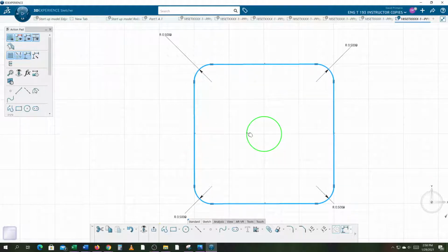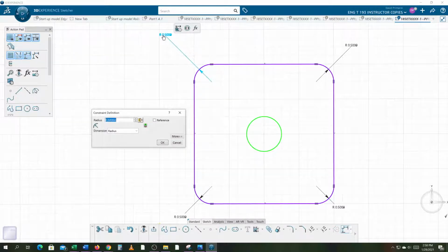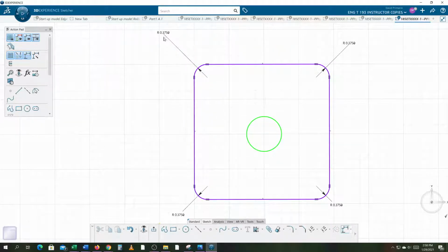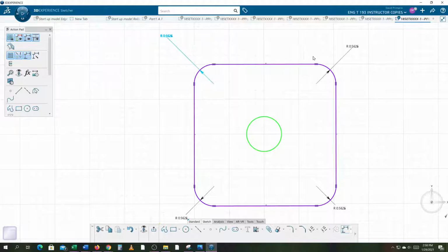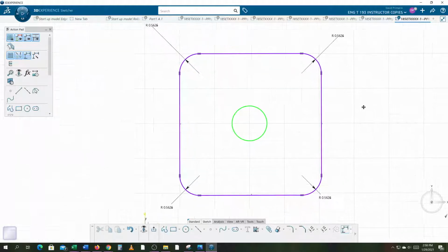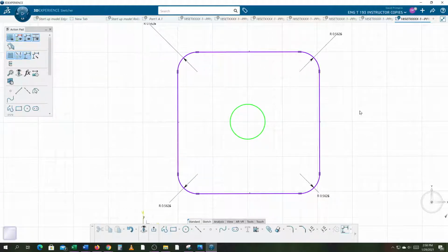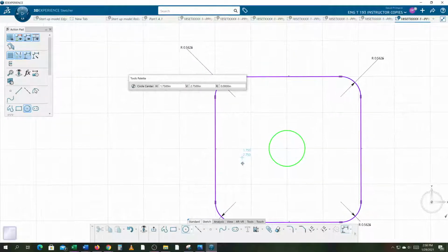So what would be better is if these radiuses were all 9/16. If you made the radius, what did I type in there? 9/16, which would be .5625 really. Okay. So now your cutter would come in here. Let's do this.